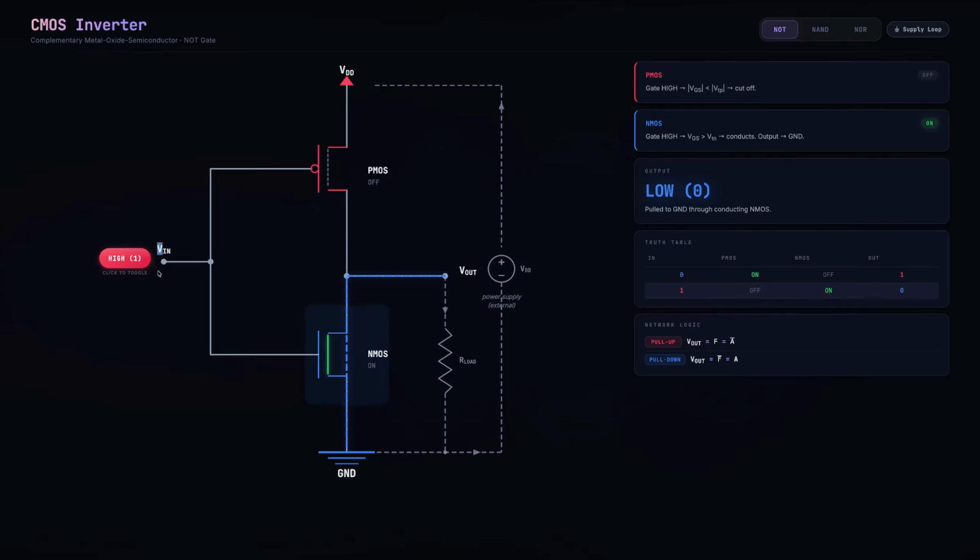On the other hand, there's no voltage drop across a wire, so the high voltage goes to the input of this NMOS gate, which turns it on. When that turns on, that grounds the output, so the output voltage is 0, and there would literally be no current flowing in that particular circuit. So that's the idea of how an inverter works. Let me turn this back off. This is the schematic that you would typically see.